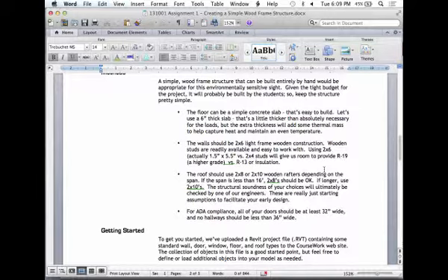Another material you might have here is shingles. On some of the older houses, you have cedar shingles that are painted or stained, something like that. But the cool thing is, there's 3 or 4 different wall types that are used here on campus, but the way we're going to model it is very similar. We're always going to keep that wood frame, the core, in line here. And we'll just swap in and out different materials on the outside. We'll do that by changing wall types. And I'll show you in the starting point, a lot of those wall types are already defined for you, and then we can start customizing it to create your own wall types. That first template has the different wall types in it. Okay, so we'll have some walls. And there'll probably be a wall over here too.